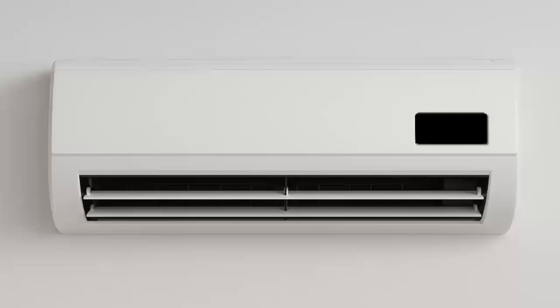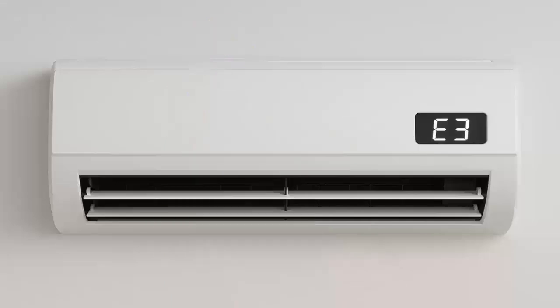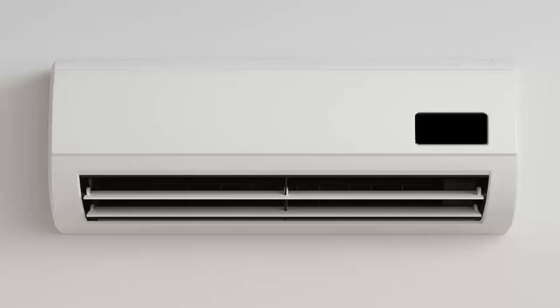To detect this condition, A. Measure the compressor's power consumption using a clamp meter. An abnormally low current draw may indicate a refrigerant leak. B. Look for oil stains on the piping and connections of both the indoor and outdoor units. These stains usually indicate a leak point in the refrigeration circuit.